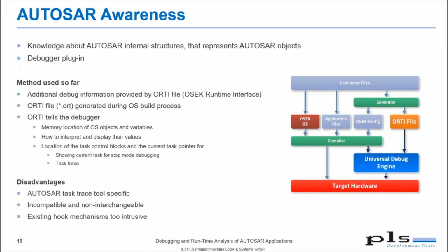As an example, if you want to analyze the runtime behavior of your system, you will use trace that is provided by the microcontroller. This is a microcontroller feature, and it's a very common technique to observe the runtime of your application without influencing it. And the microcontroller captures trace information, and or the debugger captures this trace information. Then you can analyze the timing based on these trace data by, for example, a timing tool from a different vendor.